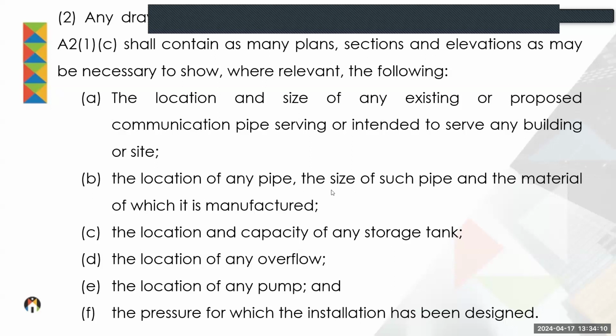Location of overflow is quite important, especially in swelling clay and dolomitic areas, because you don't want overflow water to come and pond near the foundations.